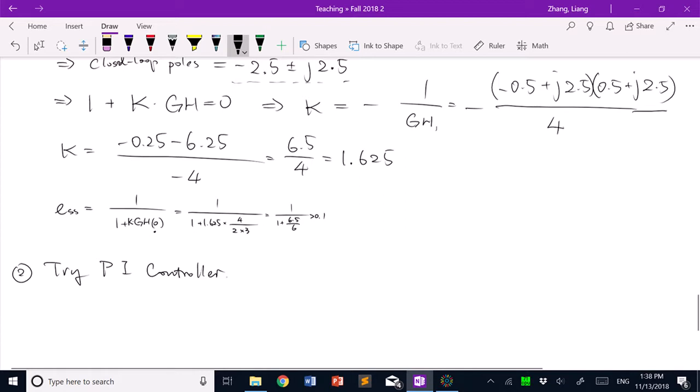But when you have a PI controller, you basically have two parameters. And determining two parameters simultaneously can become rather complicated, right? You have 2 degrees of freedom. You have to see how the two parameters interact with each other, and that's not really convenient.